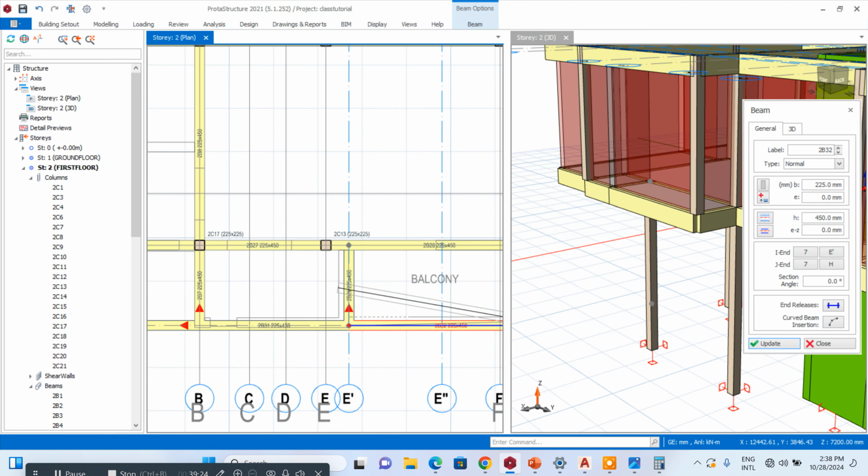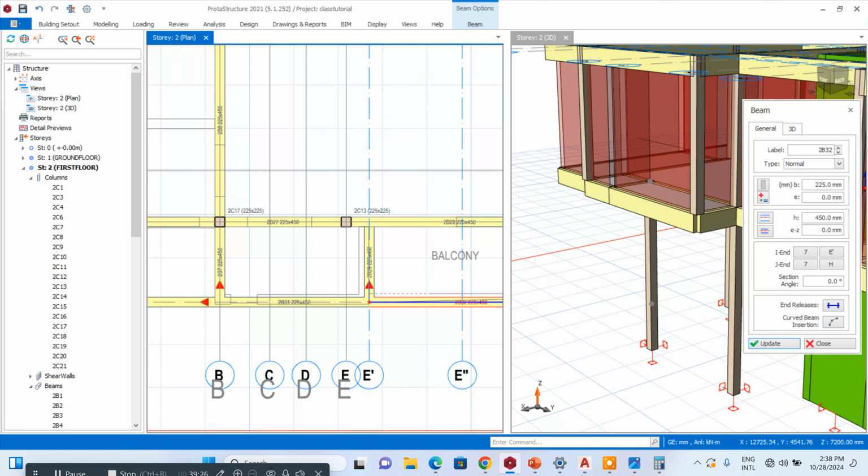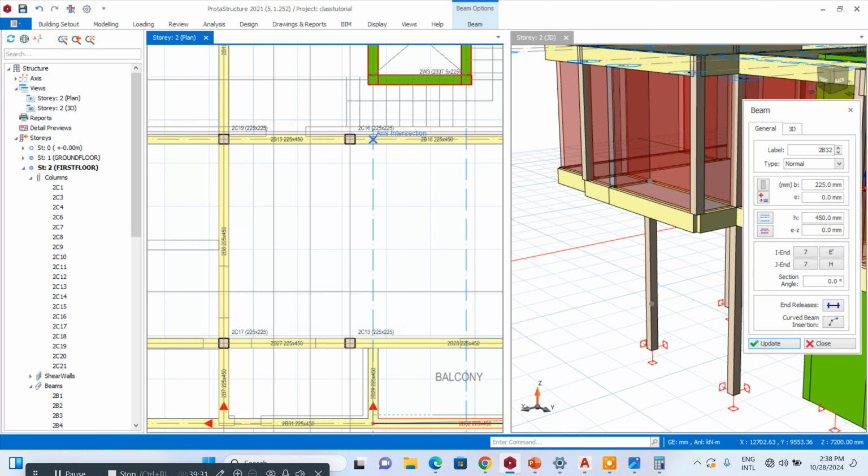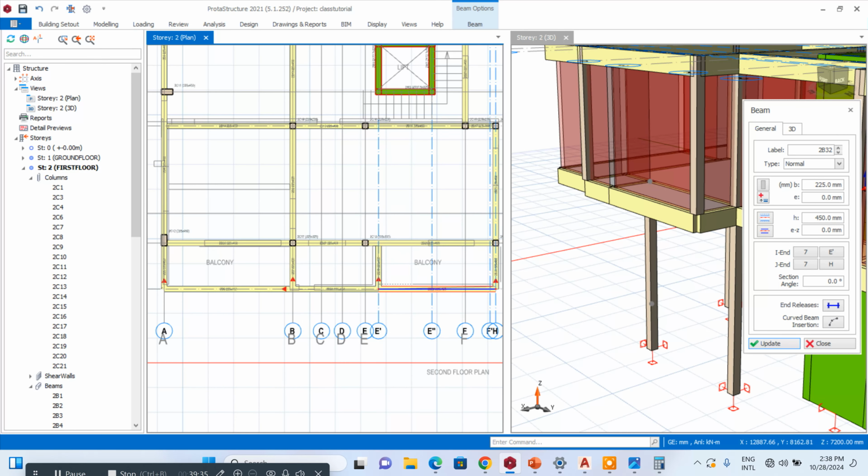Yes. So when you have a beam of this nature, a beam that is just tied without a support extending at the other end, it's likely that this type of beam will always fail. So it's better you have an extension here that will anchor at this place so that it will give it more stability.